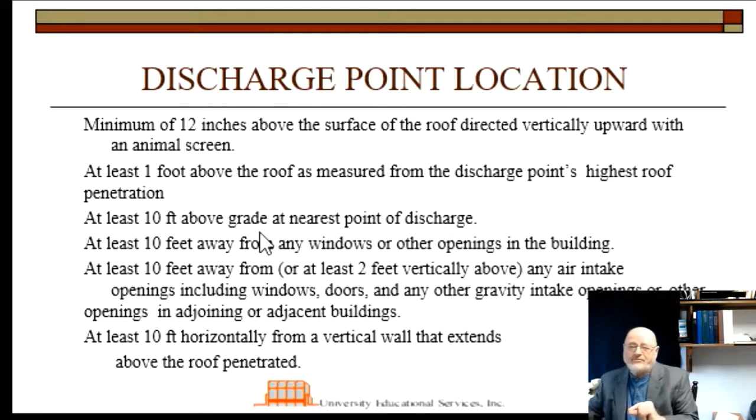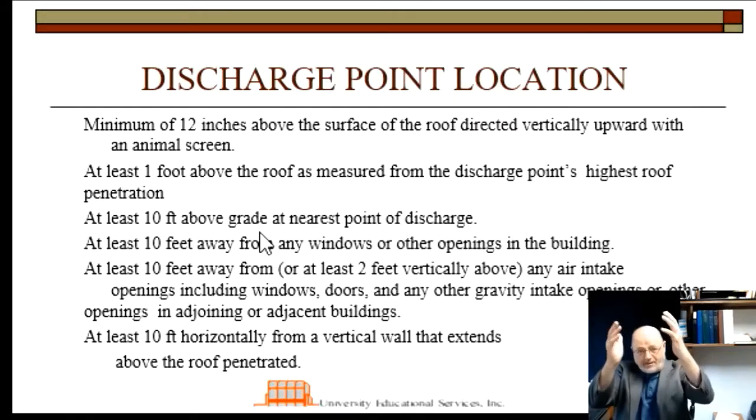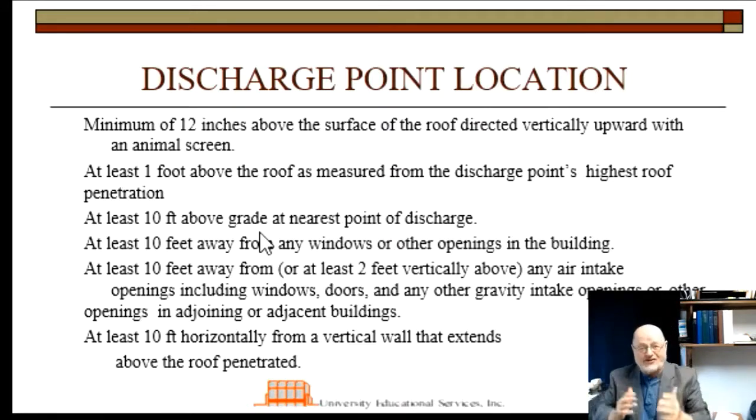The discharge point. I wanted to make a couple of remarks on this because remember that the soil gas radon concentrations can be in the hundreds and in the thousands. So you're going to be venting this gas up and out through an exhaust pipe, in effect. And it's going to come out of that exhaust pipe with concentrations in the hundreds and thousands typically. So you don't want to have that exhaust pipe coming out right near somebody's window, obviously, because a lot of that radon could easily get blown back into the building. That typically is called re-entrainment. But you want to avoid that.